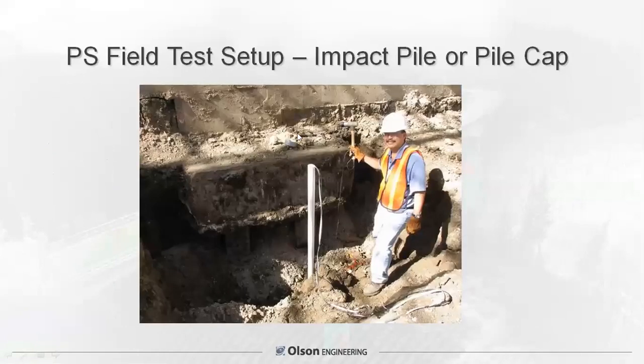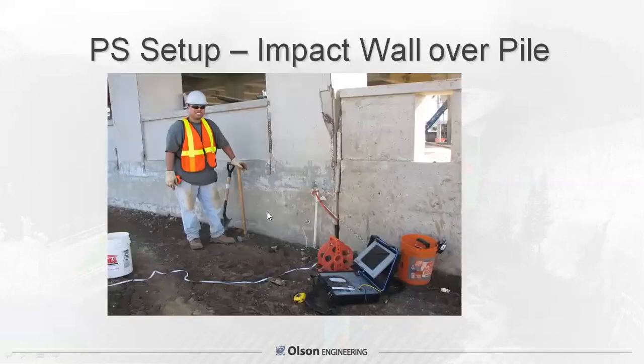Impact the structure. In this case, he's impacting the top of a pile cap. You can see these piles down here. By the way, the test in this case is going to be measuring the deepest pile. You're not going to be able, when hitting a pile cap, to differentiate one pile from the other. It's simply going to tell you which of these two piles is the deepest. And you can see our borehole is here. It's got a tape measure to measure the depth and a hydrophone cable going down.